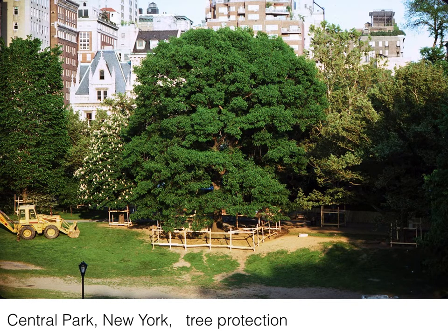Trees, we don't know a lot about them. A few simple things: there's the trunk, the roots go down, and a very important thing to be aware of is that the roots will usually go out as far as what's called the drip line. So you've got the canopy of the tree, and the water comes down on the edge, and that is how far the roots will go out. So don't kid yourself that you're going to be able to build right under a tree, up to a tree trunk, and have that tree survive.